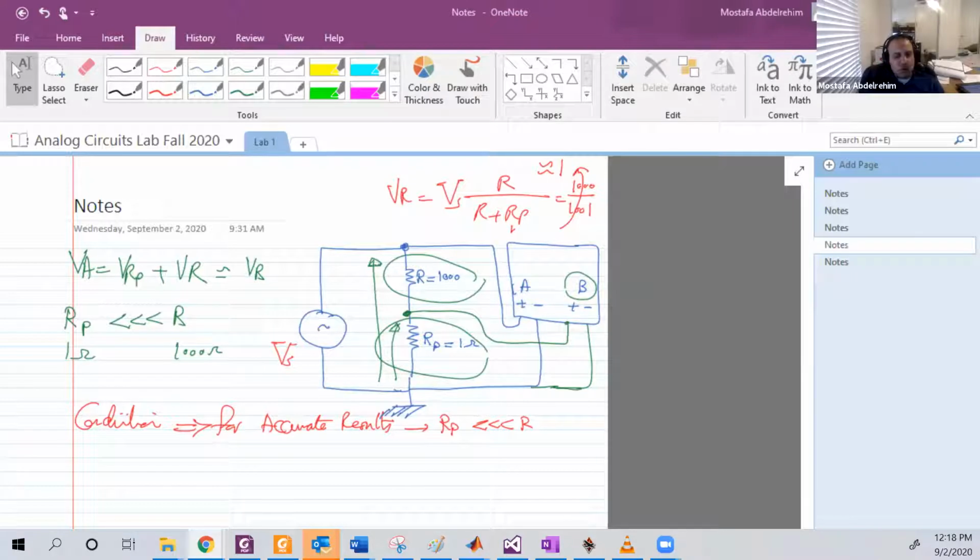Okay. Now let's do the experiment again. Let's run. We shouldn't see any difference because R1 is very large compared to R2, which is 1 ohm. So you will not see a real difference. Let's open the oscilloscope. It's exactly the same, right? This was the last figure that we showed in experiment 2. If you measure, you will also find 1 kilo ohm, approximately, of course.